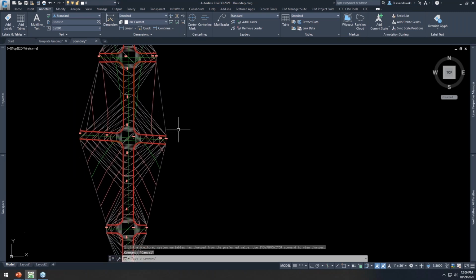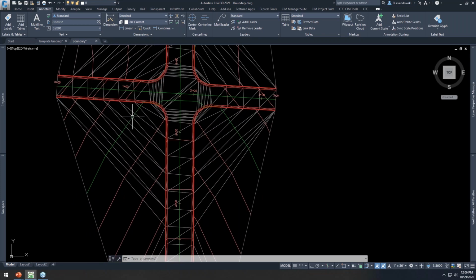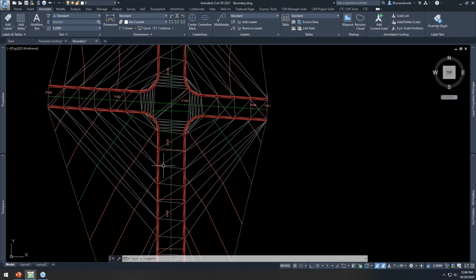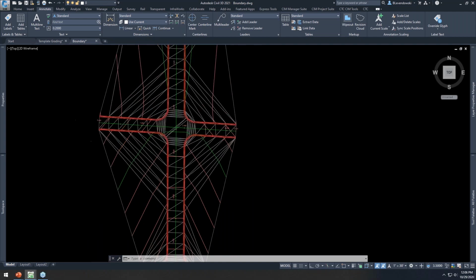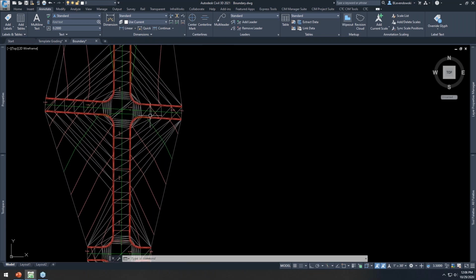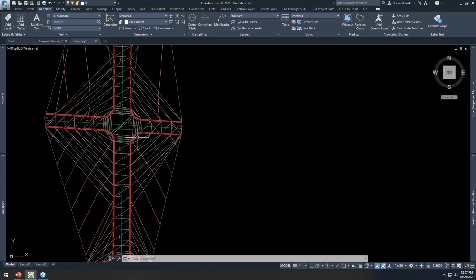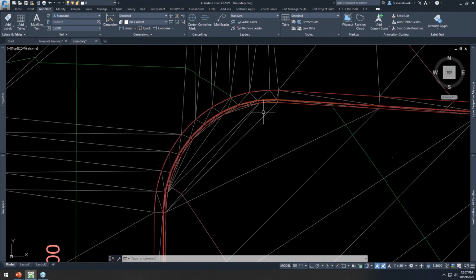Now here I've got a very clear example where I've got feature lines that were used to grade out curb lines, and I get all this excess triangulation across there. Okay. Now maybe you're using a corridor in this example, or what I've seen from a number of folks is they're starting to use AutoGrader to grade out simple roads like this or intersections, because it can automatically grade all those curves for you.